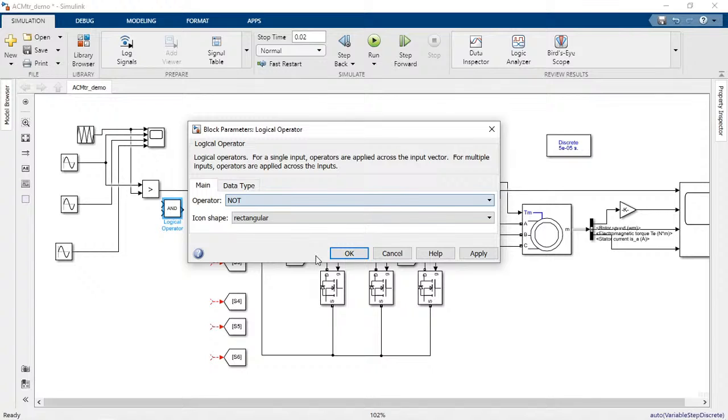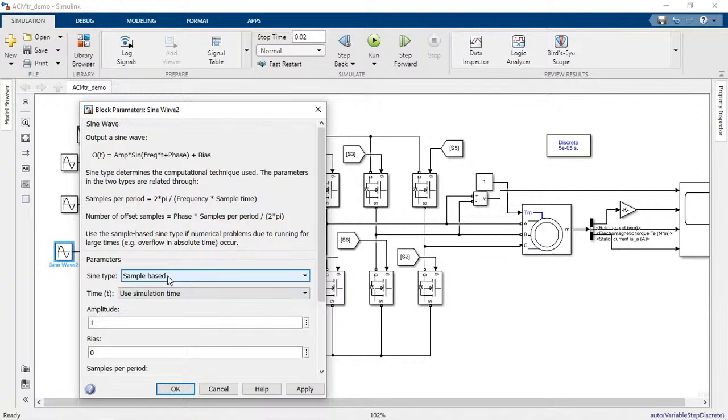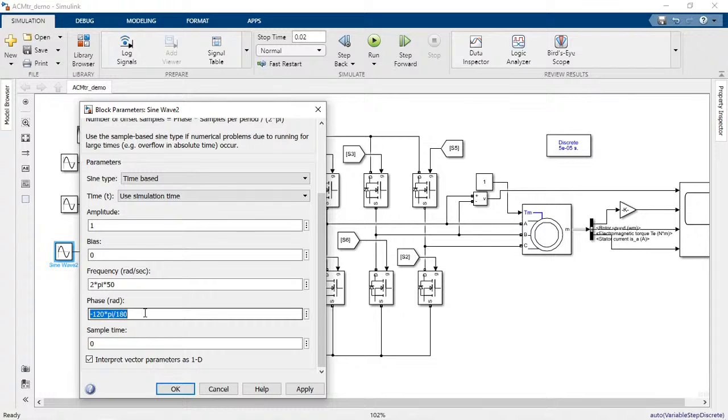Right? So now again we have to generate a C phase. So C phase is 240 degrees. So take minus 120 or 240, just to take it. So take this value, compare with the carrier waveform, and straight away this is the S2.